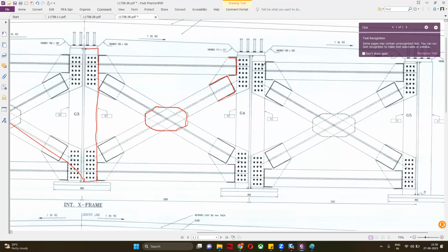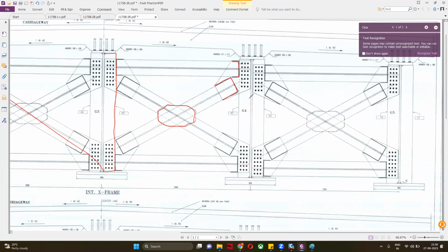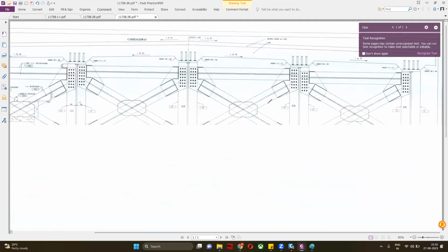For local buckling, whatever we have discussed, what will we provide? For local buckling, we have this stiffener. Is it a longitudinal stiffener, sir? Not the longitudinal, this is the transverse stiffener on the web. Longitudinal will be perpendicular to it, and will look like this. This is the transverse system. Longitudinal will come like this. This you will see very rarely.